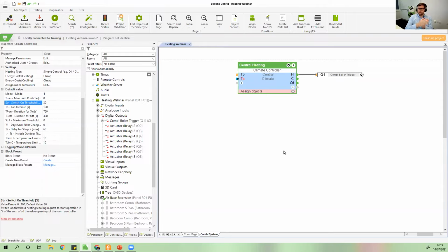An example that I would use might be a WC. If you built a WC into the far end of your house, maybe where your entrance door is, it's going to have maybe 2 or 3 externally facing walls. It's a very small space. That room may naturally get a lot colder than the rest of the house. But if you turn the heating on just for that room, because that's the only room that needs heating, it might be up to temperature in 20 minutes, and then your boiler would turn off.